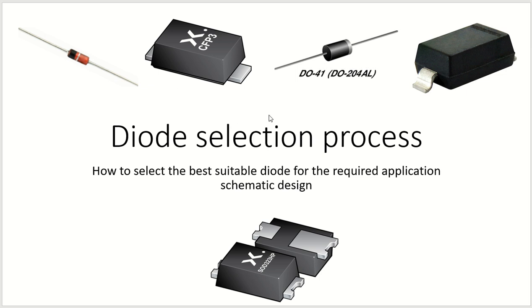You have power supplies, so you will be needing some switching diodes. You have a bridge rectifier, there also there is a diode which is going to work for rectification purpose, so AC to DC. So almost any circuit you take, you will be requiring a diode. Have you ever considered whether simply selecting a diode is enough, or do we need any extra capabilities to select them? You cannot select a diode of, let us say, 200 volt rating and 1 ampere rating if you just need a 20 volt signal with 20 milliampere current rating, right?